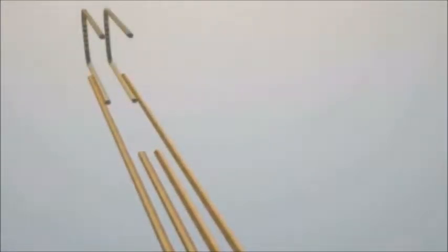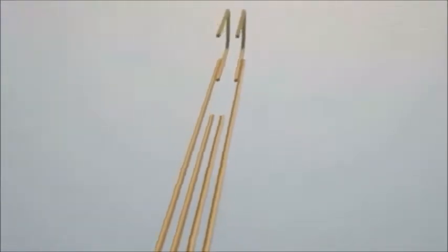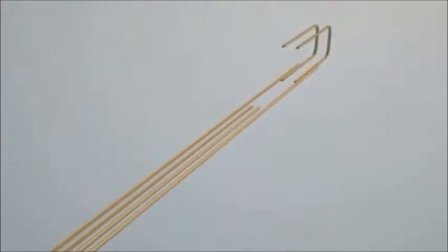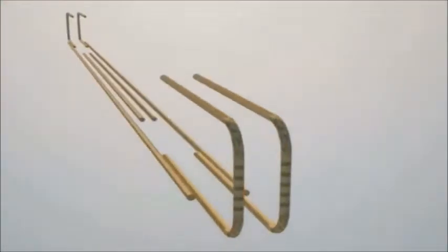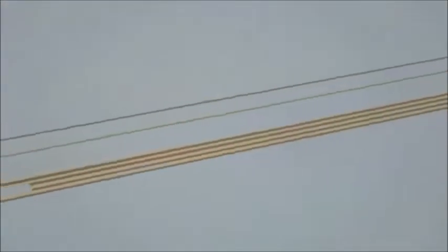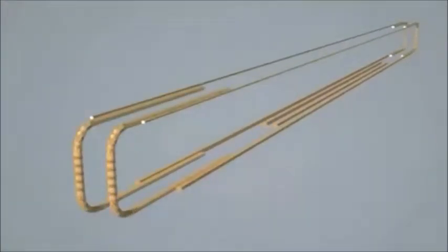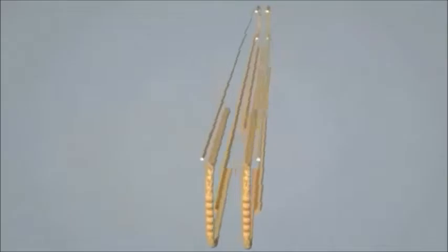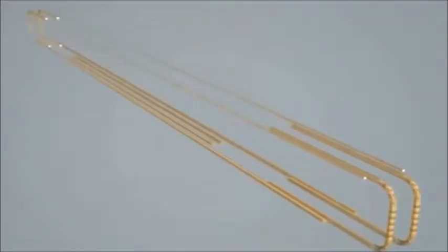Next, at the end of each side of the ground beam, a C-shape steel bar will be used, which is also the same size as the steel bar used at the bottom of the ground beam. After that, another 2 steel bars will be added toward the top of the ground beam. The diameter of these steel bars is smaller than the previous ones. The steel bars will be arranged the same as described in the drawing plan.